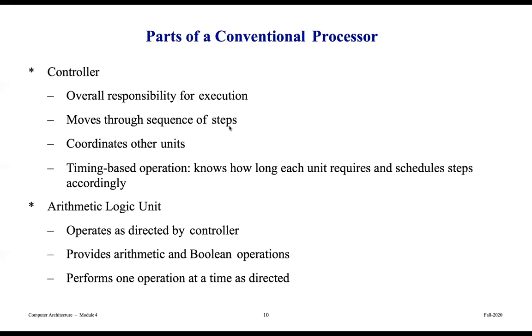There are times when it needs to be reading memory, writing to memory, or have a couple of operands that are needed to do a specific step as it goes sequentially through each of the instructions. It's timing-based: it knows how long each unit requires and schedules steps accordingly. So it's like the conductor of a symphony, if you will, or the coach of a team, keeping everybody in line and making sure that they're going by agreed upon rules, and executing things in a smooth fashion.